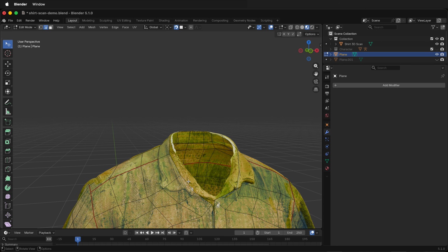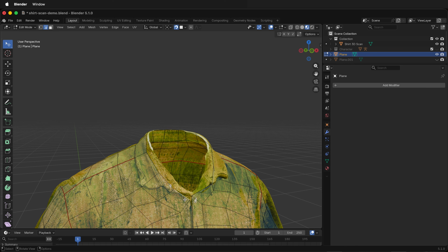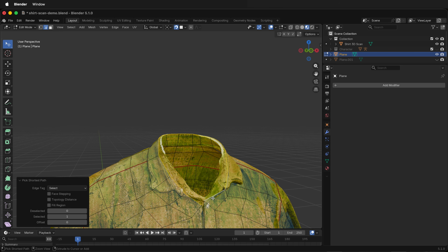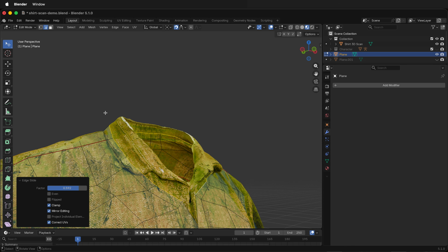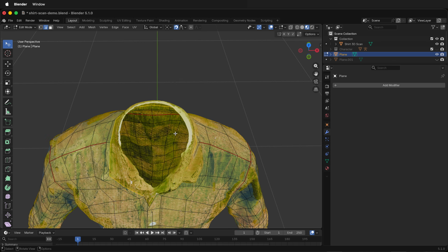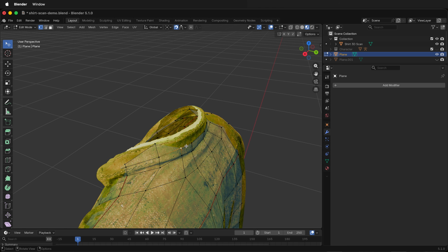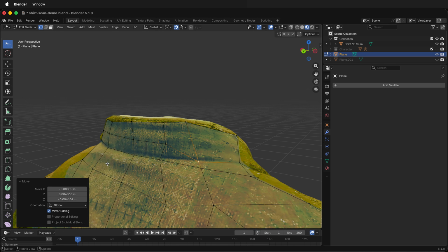And actually the collar stand needs to come up off of this. So turn off snapping. And again, you want to do this at the end because it's kind of a separate piece. But if I slide this down, pressing GG, so that it only has those pieces, and then I press E and bring this up, and then put these pieces where the top of the collar is. Sometimes you need to look at the back to find out where all your vertices are.